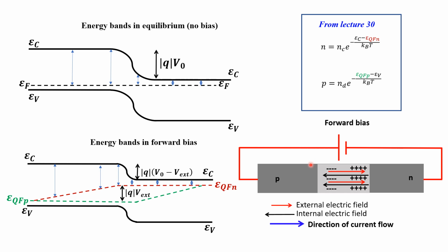So that means that we're going to have recombination. We have more free electrons than in equilibrium, and there are lots of holes for them to recombine. So these electrons will suffer recombination, and they will disappear. The free electrons will cease to be free electrons. So the concentration of free electrons will decrease as we move away from the depletion region. And that is why this distance has to increase as we move away from the depletion region. This is why the Fermi level lowers.